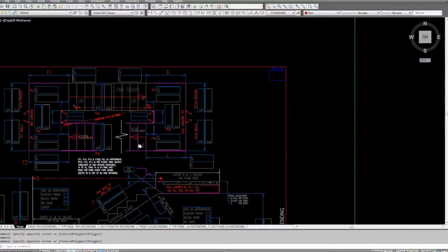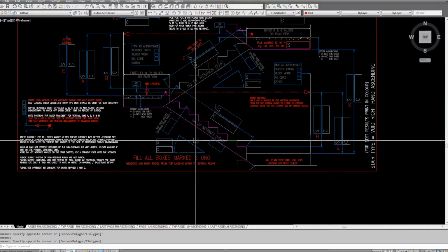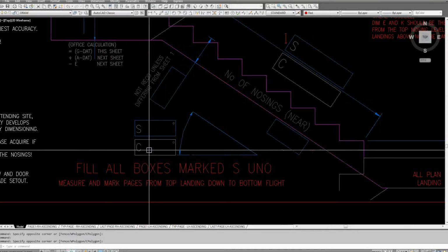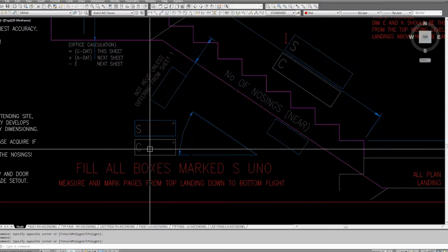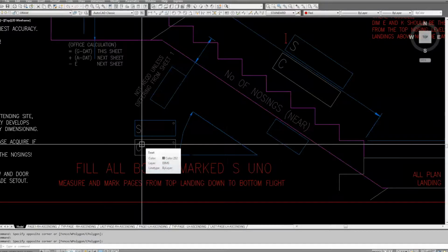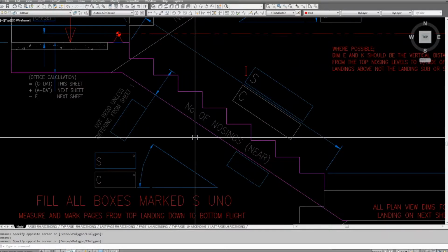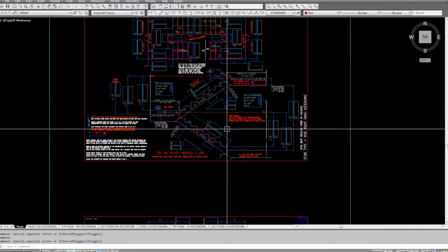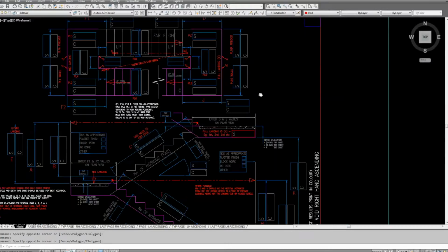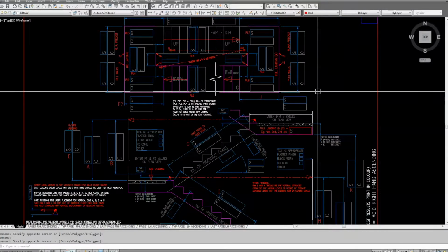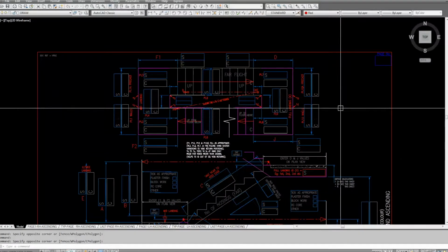That gives me an idea that the stairs have gone in something like, if I know it's 30.2 degrees theoretical, the C value, and it's coming out at 34, I'm going to remeasure it, and flag it up as incorrectly installed. And believe me, some stairs are so badly installed it beggars belief.